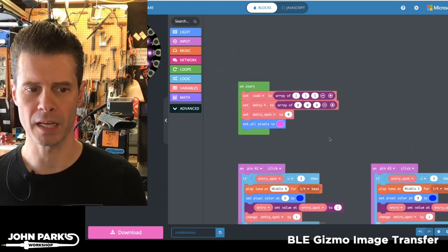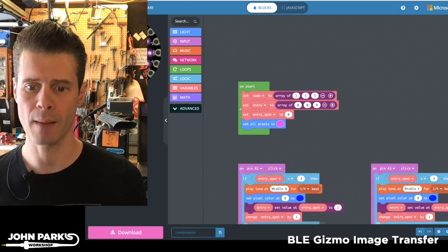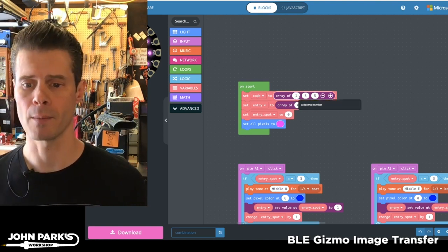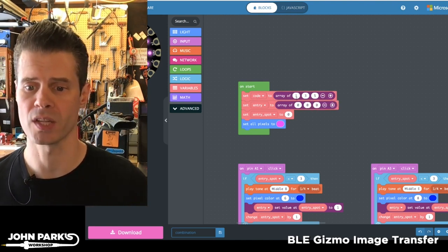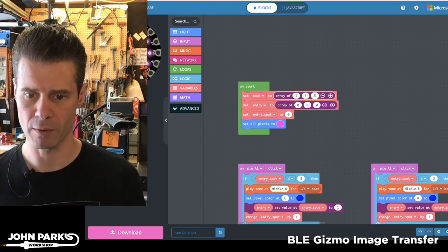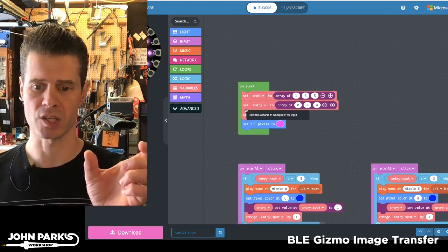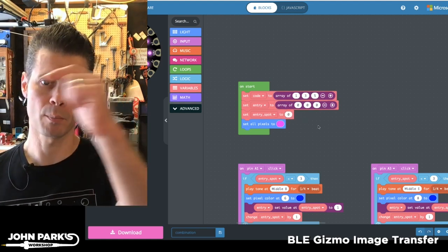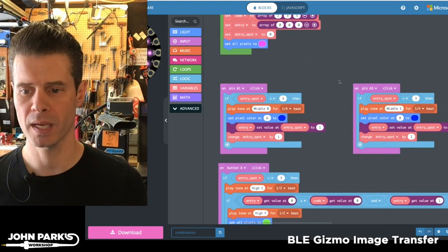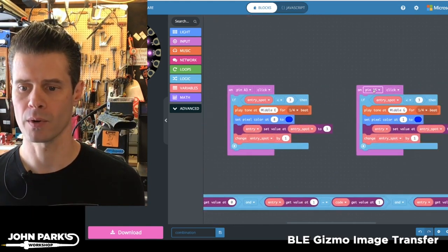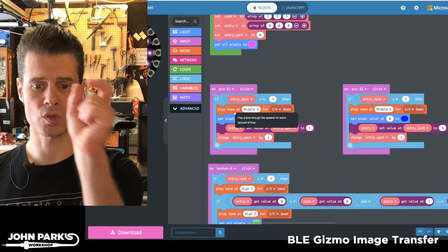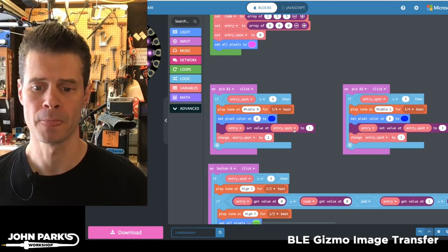There are probably plenty of ways, but the way I chose to do it was I created a couple of arrays. I have one that's called the code, and it's an array of 3 members, and they are 1, 3, 5. So that's the order that I decided my combination is going to be right now. And then I have this empty list of 3 zeros that is where I'm going to plug in my attempts. Then when I press the A1 pin, the A3 pin, or the A5 pin, it enters into one of those slots, depending on the order we press them, a number.